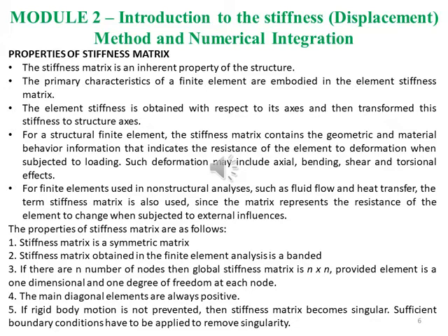In structural problems it is the modulus of elasticity that forms the stiffness matrix, but in fluid flow and heat transfer problems, the matrix represents the resistance of the element to change when subjected to external influences. So fluid-related properties and heat-related properties will be inbuilt in the stiffness matrix.